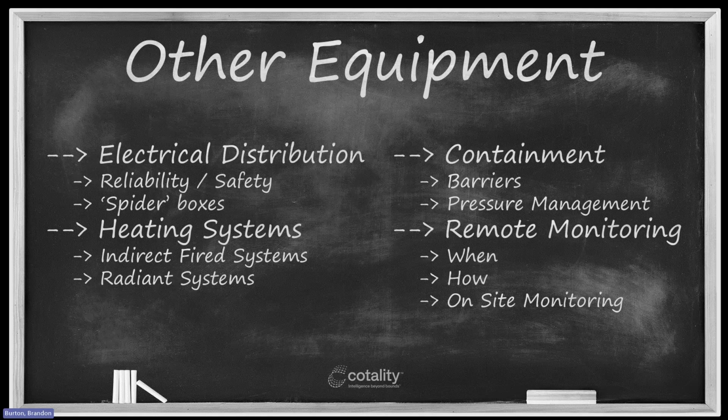Containment is something that I don't think is understood well in our industry, but it's something that should, as a specialty drying system, be considered. Anytime that you have an affected area that measures less than half of the total space within an environment, in my opinion, containment is a good way to be more efficient with your drying approach by reducing the amount of air that you're managing. There's kind of a give and take there.